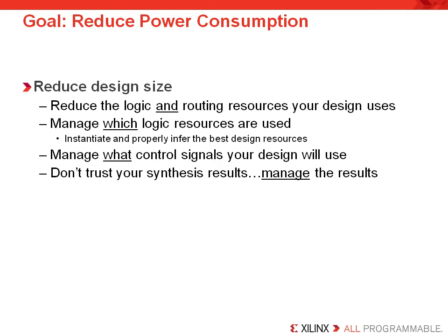To do this, you'll need to be comfortable using the core generator and instantiating components from either the Xilinx Unified library or with the core generator. As you'll see in a couple of slides, you will also need to manage your control signal usage. You will also need to be comfortable using your synthesis tool to infer the optimum resources, and this will require you to be able to verify which resources are used by using your synthesis tool schematic viewer.